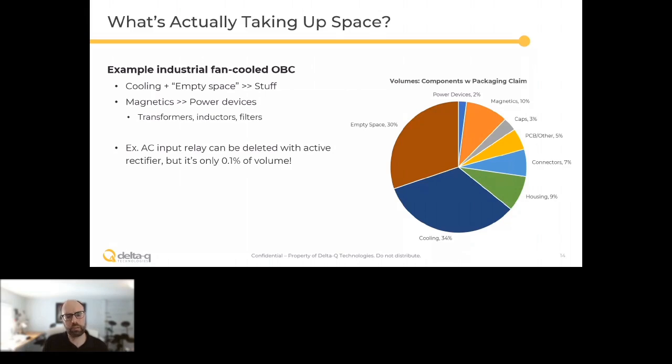If you compare it to the maximum length, width, height. The housing itself, the walls and the shape and the mounting feet, connectors, that occupies a lot of space. And then you're left with about a quarter of the volume that is actually the power converter itself. I should say that I've actually counted some space in these categories.